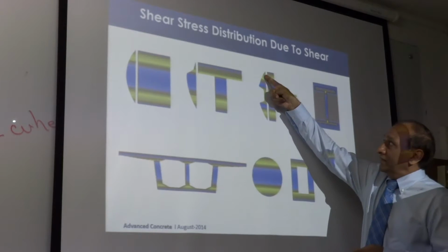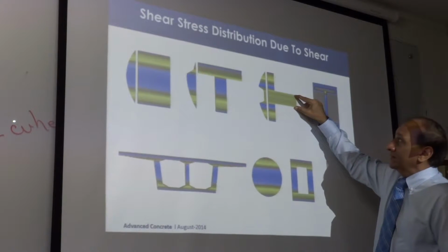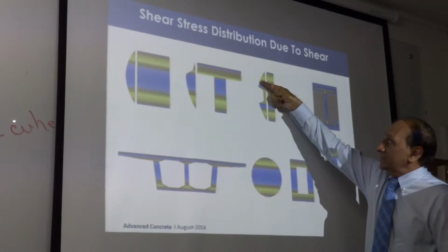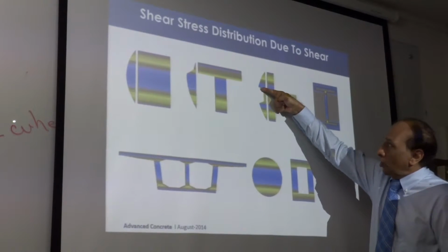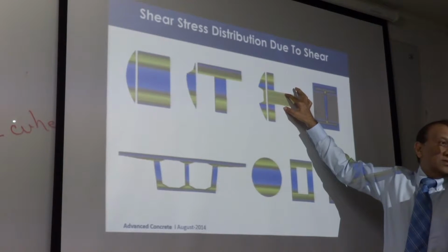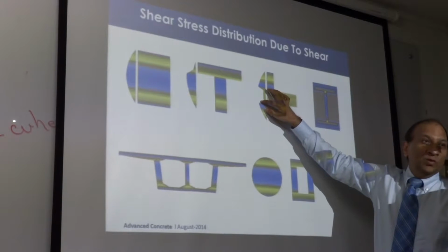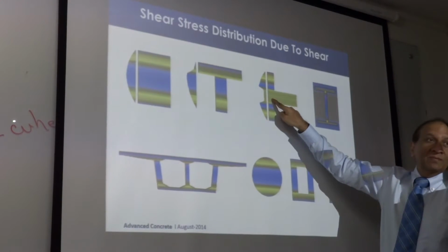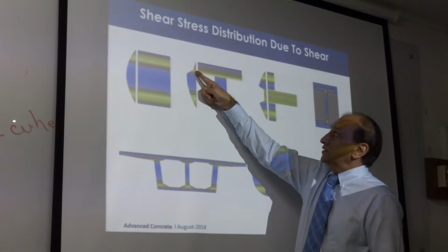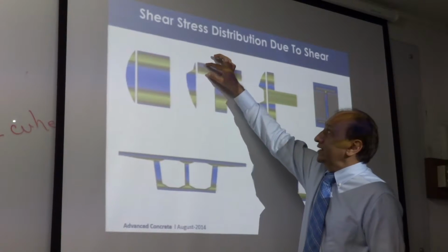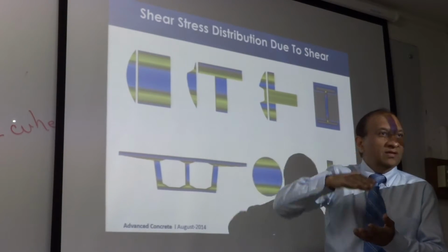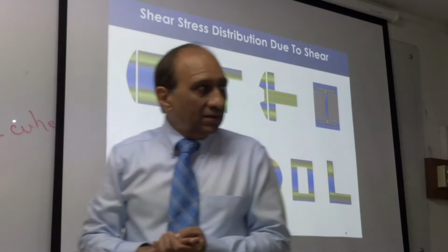And also, we have this kind of variation because there's more area here, so the stress drops, right? Normally, if you don't have this one, this will continue like this. But this is dropping because there's more area here to take care of that force. So the stress drops. But the total force is actually more here. Stress multiplied by this web area, correct? But it's not so efficient. So that's why, when you increase this one here, because there's suddenly a small area, stress increases at that point because the force must be maintained, right? Clear?